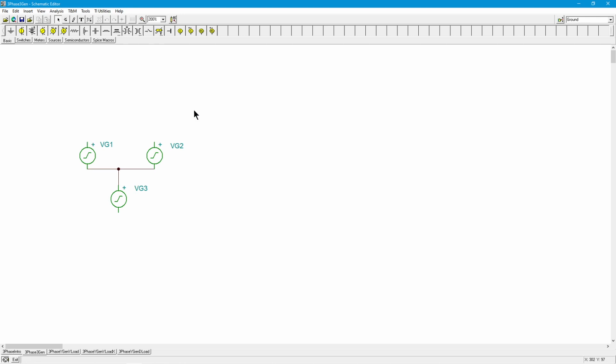And they say, okay, so now I got my 3 phases, phase 1, phase 2, phase 3. Well, if you look carefully at this, you realize this is a major error. Because look at the reference polarity for generator 3. That's a plus up here, right? That's the plus going to your common point. So you've actually thrown in an extra 180 degrees. So this was 240, right? Plus the 180. Well, sorry, not what we want to do. How do you really want to do this?